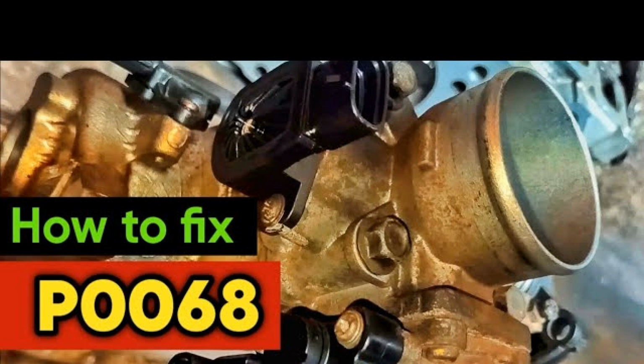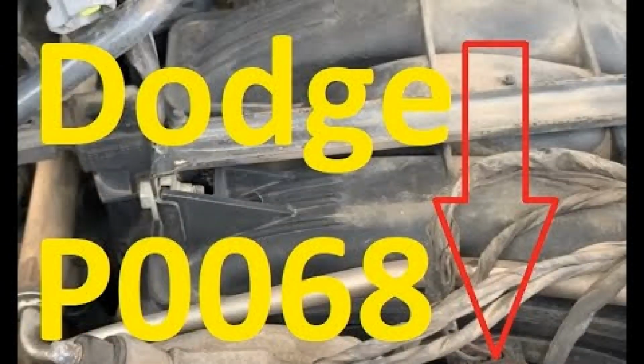What does P0068 mean? The Diagnostic Trouble Code, DTC, P0068 stands for MAP/MAF, Throttle Position Correlation. If the readings from one or more of these sensors contradict the data presented by the other devices, the vehicle computer, aka the Powertrain Control Module, PCM, records the OBDII fault code P0068. A discrepancy in the readings of the MAP, MAF, and TPS sensors can trigger code P0068.